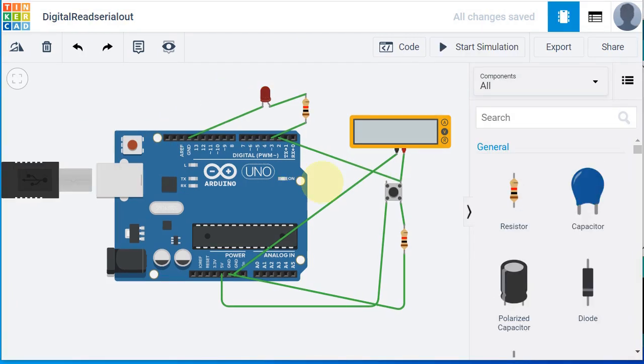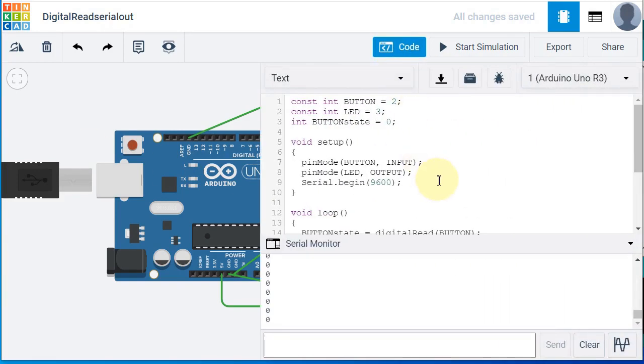Now we'll see some serial communication also. Say for example, if you want to send the status of the LED, whether it is on or off, in a serial port, or you want to communicate with some other Arduino or some other computer, the communication mode will be mostly serial communication. So in this Arduino already serial communication is available. So just see how we are able to code the serial communication to send the status of the LED button. Let's check how the code will work. So just go to the code. Here I opened a serial monitor. It is below in this text. On the bottom of the text you can see a serial monitor.